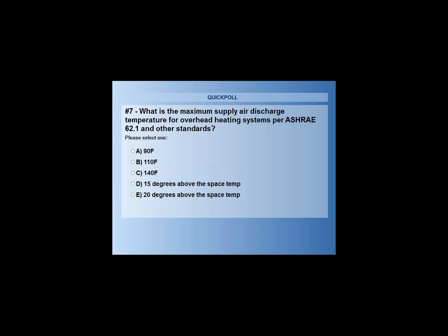So in that case, I can use hot water coils or electric resistance heating or gas burners or radiant floors or any other type of heating source I want to supplement that heat pump and get that fantastic heat pump energy savings most of the time, not necessarily all of the time.